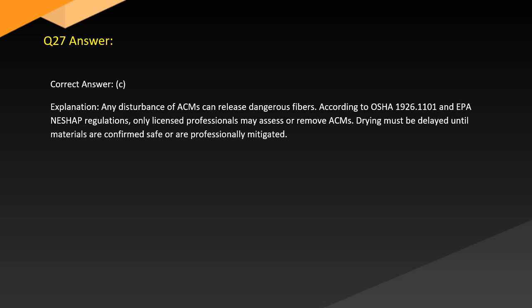Answer. Correct answer. C. Explanation. Any disturbance of ACMs can release dangerous fibers. According to OSHA 1926.1101 and EPA NESHAP regulations, only licensed professionals may assess or remove ACMs. Drying must be delayed until materials are confirmed safe or are professionally mitigated.